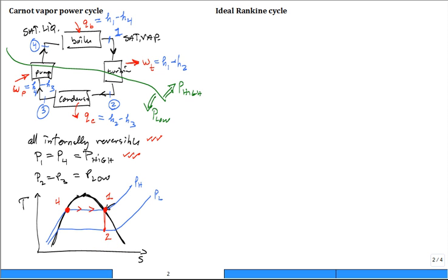True? Now, we go to the pump. I know we're going to be condensing, but you only condense so far such that the pump is just like the turbine. It's isentropic compression. So it's straight below, 3 is straight below 4, or 4 is straight above 3. Either way you want to talk about it, but okay.